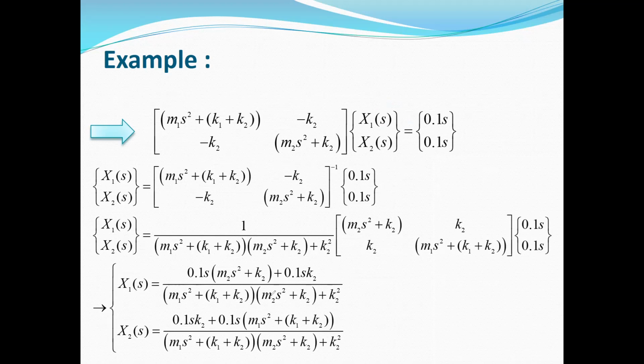So x1 and x2 can be obtained, and now we can substitute the numerical values for m2, k2, m1, and k1, and simplify these equations and obtain the subfractions similar to the previous example, and obtain the response by using the inverse Laplace in time domain.